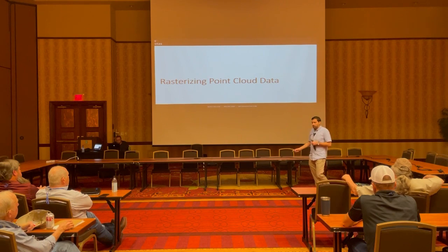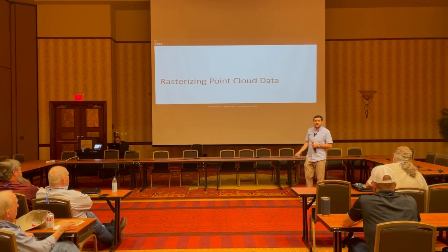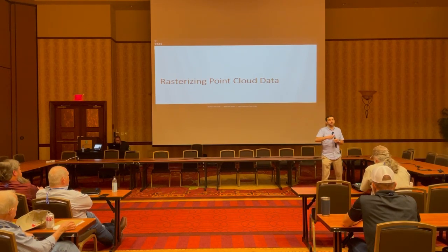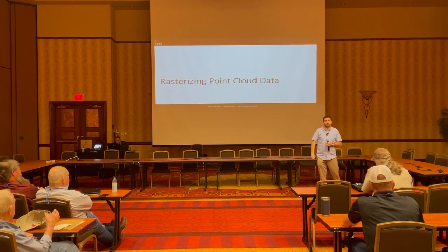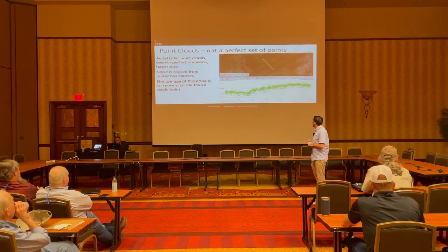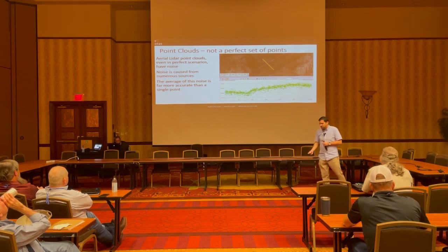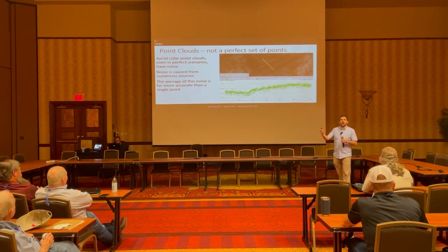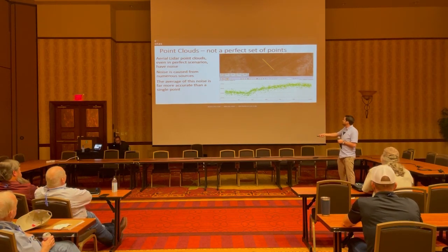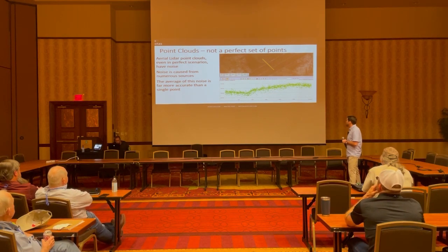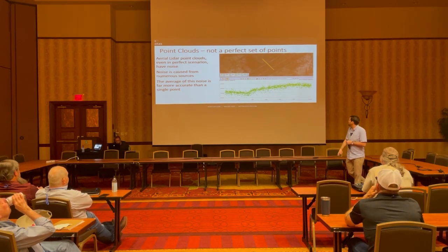So next up then is rasterizing the point cloud data too. And this actually applies both to photogrammetry and LiDAR as well. This is not just a LiDAR thing at this step. Point clouds, they are called clouds. They are not a perfect set of points. They have some noise to them. Aerial LiDAR point clouds, even in perfect scenarios, have noise.